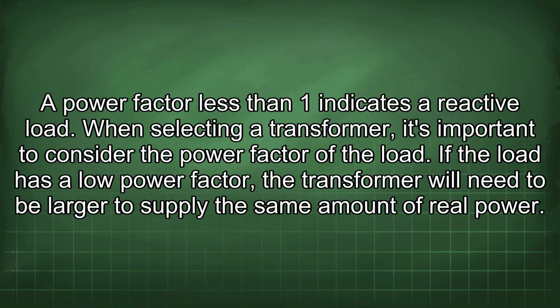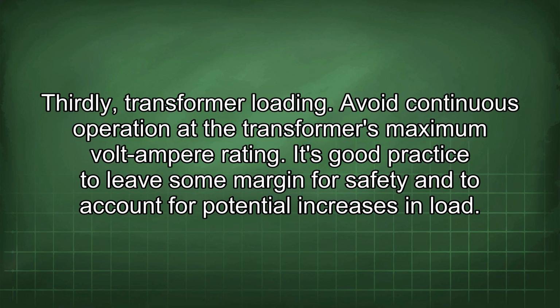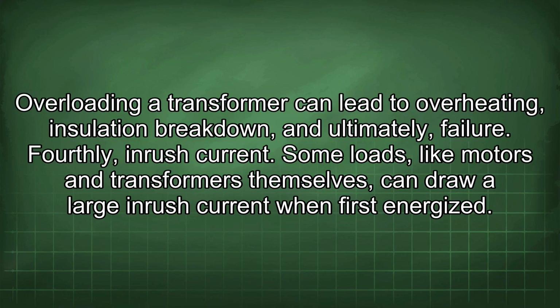If the load has a low power factor, the transformer will need to be larger to supply the same amount of real power. Thirdly, transformer loading. Avoid continuous operation at the transformer's maximum volt-ampere rating. It's good practice to leave some margin for safety and to account for potential increases in load. Overloading a transformer can lead to overheating, insulation breakdown, and ultimately, failure.